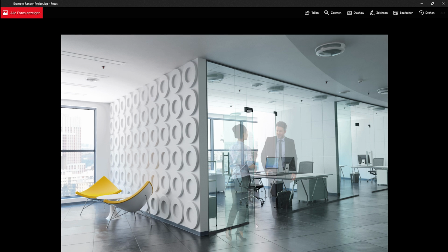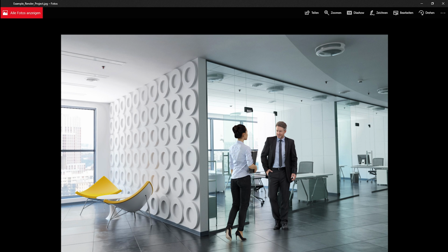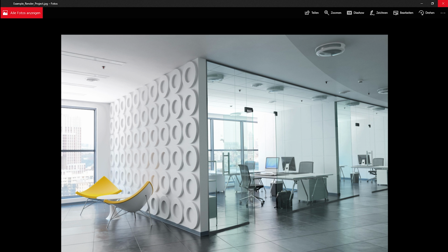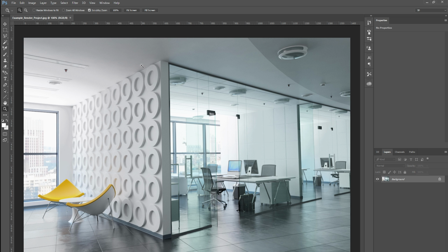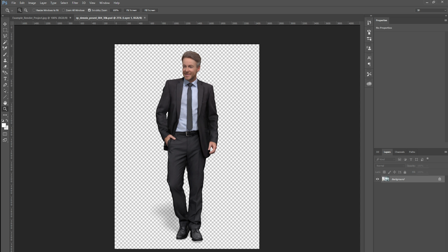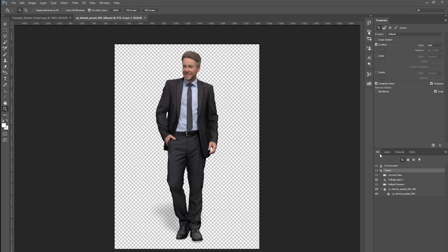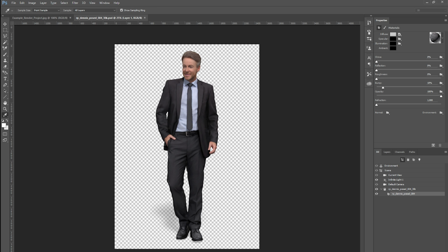In this video I will show you how to quickly enhance your already finished renders with our 3D people models in Adobe Photoshop CC. First, open your rendered image and one of our models in Adobe Photoshop. To load the model, simply select the PSD or OBJ file and open it. The PSD file comes with all needed textures already applied to the model. If you're using the OBJ file, you need to replace the diffuse texture with the diffuse map included in our package.